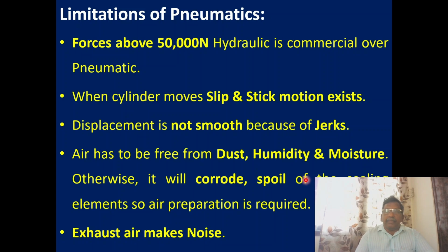The air has to be free from dust, so always you have to protect the system. You have to keep the air free from dust, humidity and moisture. Otherwise it will corrode the system and spoil the sealing elements. So air preparation is very important. Then when you exhaust the air, it creates noise.